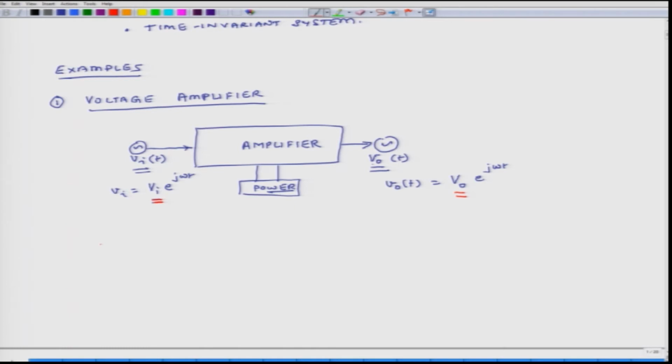So, the transfer function for the system, I can express it as H, and that is equal to V naught over Vi, because e^{j omega t} gets cancelled. Now, V naught could change with omega, and so could Vi. So, these are complex amplitudes. V naught and Vi both could depend on omega, which is the excitation frequency. So, H, the transfer function, can itself change with omega.